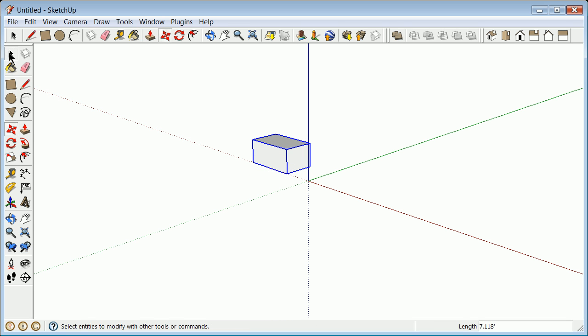All right, so that's why you have the box for the different planes. I'll show you an example of what we do now by drawing another box. Get a better idea on the modify. I'm going to draw a box, you remember. I'll make this one a square. I'm going to hit P for push. I'm going to push it up, and if you notice I jump over there, it infers the height. I'm using my left mouse button. I grab a cross, I right click, and I make a group.